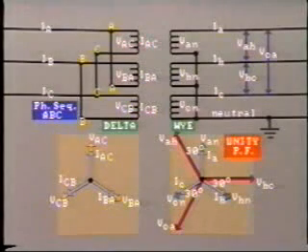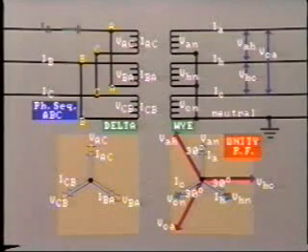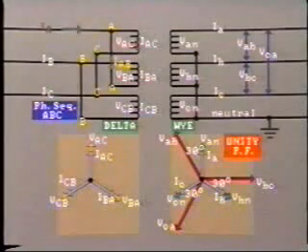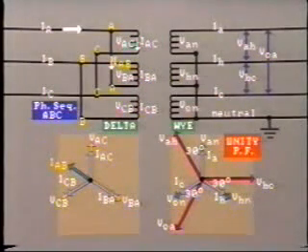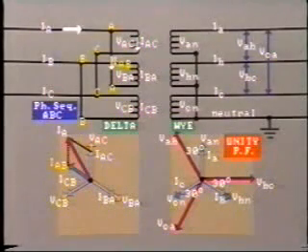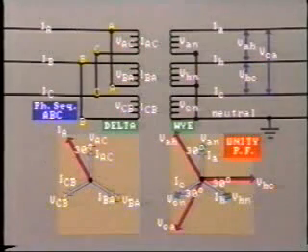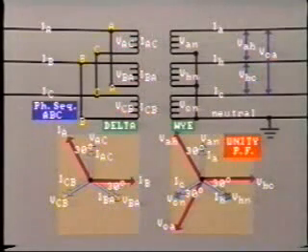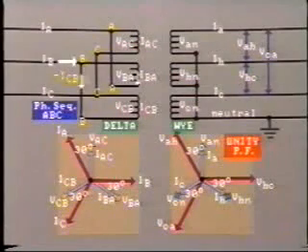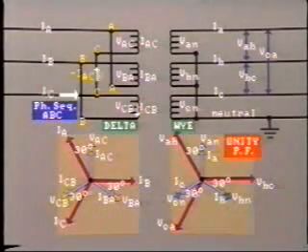But what is the current in line A, that is IA? Well, look, clearly the line current IA is the sum of the phase currents IAC and IAB, which is the reverse of IBA. Therefore, plot IAB on the phasor diagram and add IAC, which gives IA. We find by inspection that the line current IA will be 30 degrees ahead of its respective phase voltage VAC. Similarly with line currents IB and IC. IB equals IBA minus ICB, and IC equals ICB minus IAC.